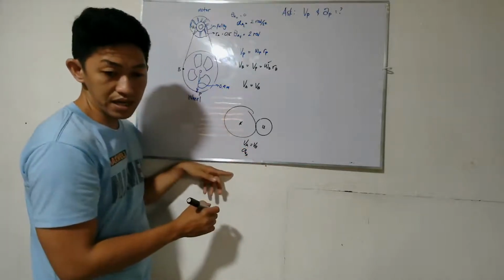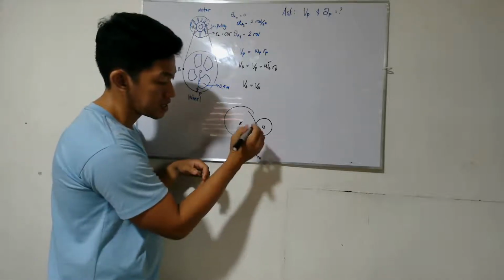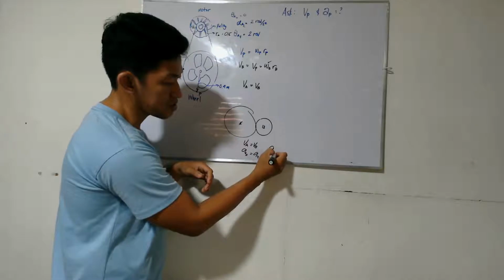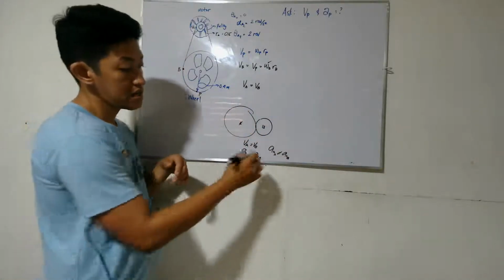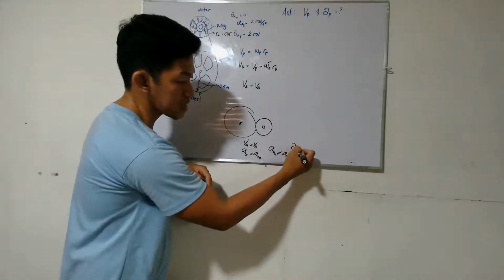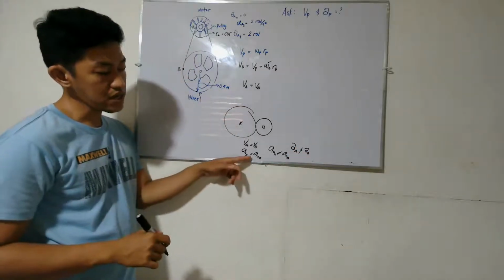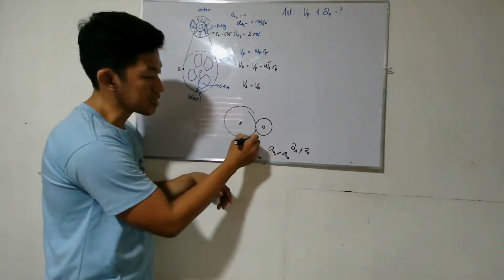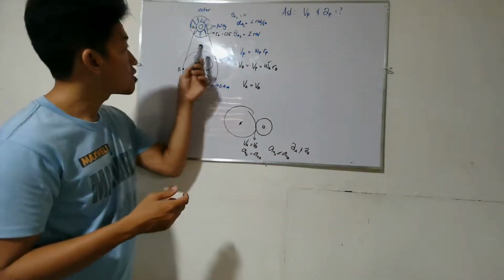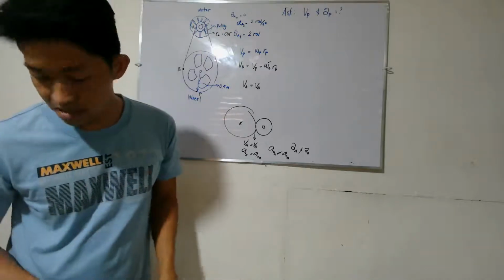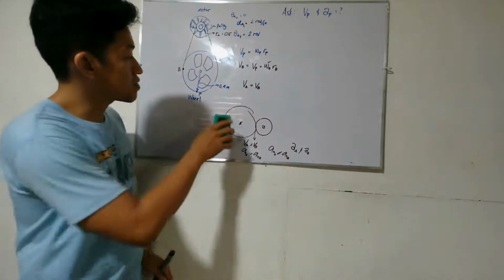Tangential acceleration of A is just equal to tangential acceleration of B. Normal acceleration of A is not equal to normal acceleration of B. Therefore, the total acceleration of B is not equal, only the tangential part is equal. Belt and gears, they are the same. Okay? So, therefore,